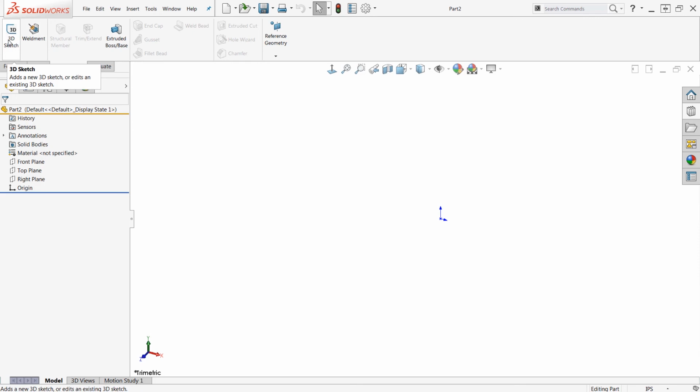That's because with the weldment structure, quite often you want to use a 3D sketch. Now you don't have to use a 3D sketch to use Weldment Tools. In fact, you can use a combination of two-dimensional sketches and 3D sketches. They don't all have to be in one feature. They can be in multiple features and things like that. The idea is you create a framework and then you insert structural members based on that framework to create your